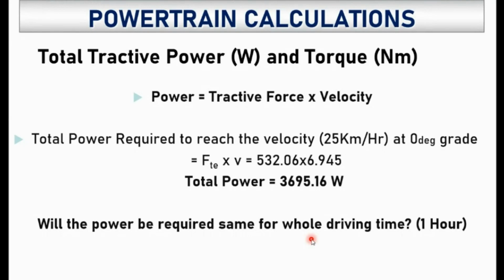So we were overcoming inertia. We had the inertia force initially. Now we overcome that, and then we kept the vehicle propelling. So now when you are already at a constant velocity, your acceleration is zero. F is equal to ma. So we may not need the power we are going to calculate continuously. So this is probably going to be a peak, if you are considering grade as well, and the total power we are going to calculate is around the peak power.